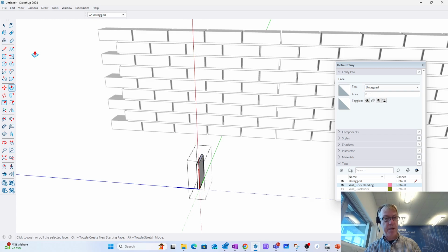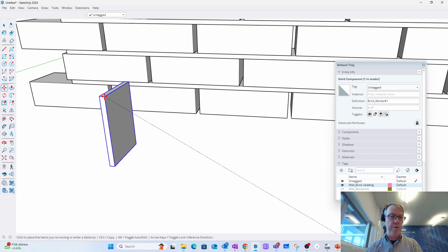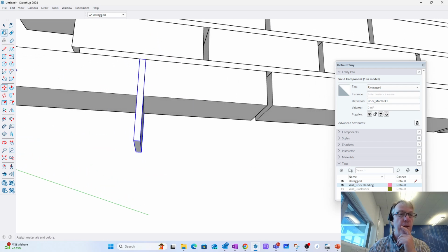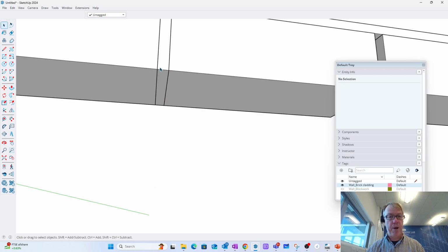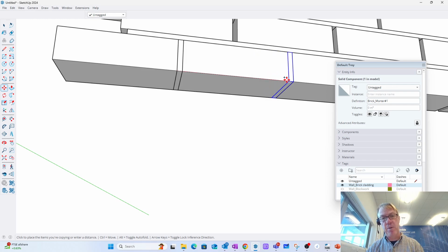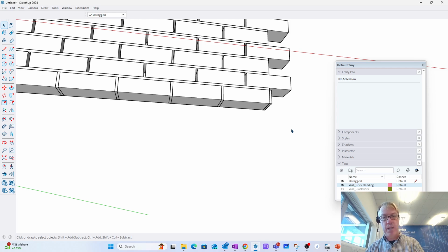I'll do that for just now. Go in here and I'll just place that in where I want it. I want it in here, and I'll go in and modify it again, the height wise, and I'll just match it up. Perfect. If I now select that, press move, Control to keep the original there, and I'll just snap it on to the end, and I'll press X, 10, enter. They should all fill up exactly where I need them. I don't really need that end one.